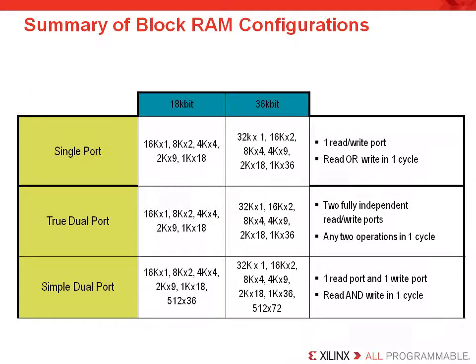This slide is showing you the supported port sizes for the block RAM resources based on your selection of the functionality for your memory, whether that is true dual port, simple dual port, or a single port memory. Now most customers just build the memory with the core generator and the GUI will provide you a list of the possible port sizes that are supported. So this helps you avoid making an unsupportable memory by having the core generator do some error checking for you.